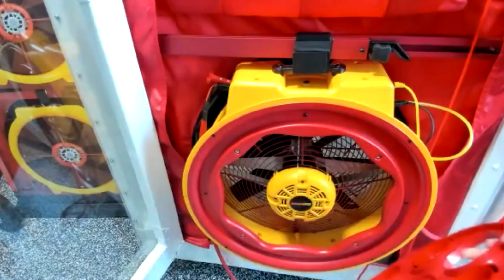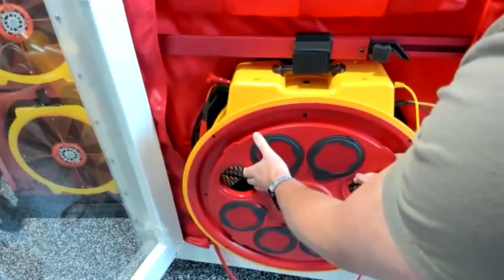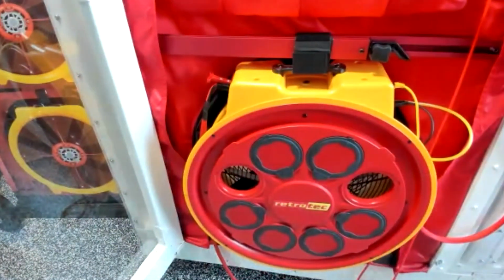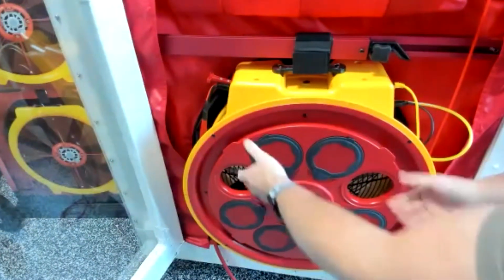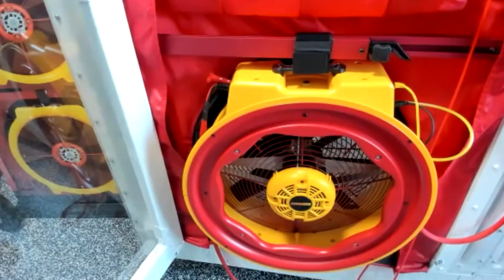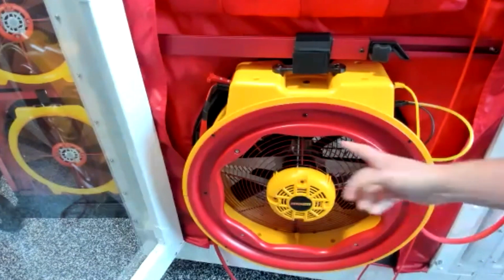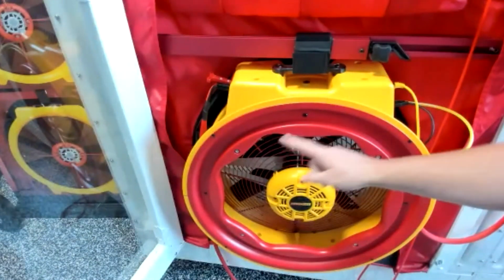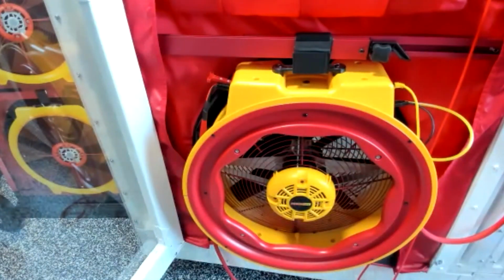What determines which range you have it set to depends on how tight the house is. The tighter the house, the smaller the opening in the fan. The leakier the house, the larger the opening in the fan. It's all about maintaining enough fan pressure while being able to hit that 50 pascal target, so you want to find that sweet spot. You can think of it like gears in a car. You want to find the right gear to make the engine work at the right speed. It's similar here.